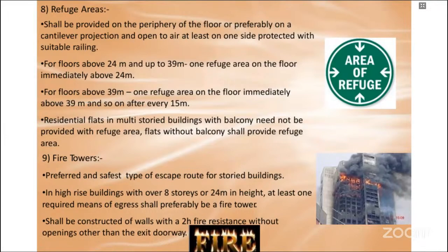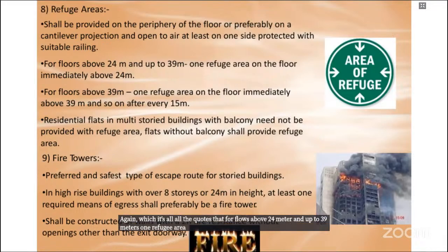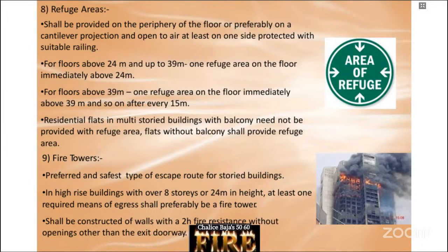Again, in all the codes, for floors above 24 meters and up to 39 meters, one refugee area on the floor immediately above 24 meters. So if my building has 40, 50, 60 floors, I have to be very clear that after 7 to 8 floors, I am providing a refugee area.